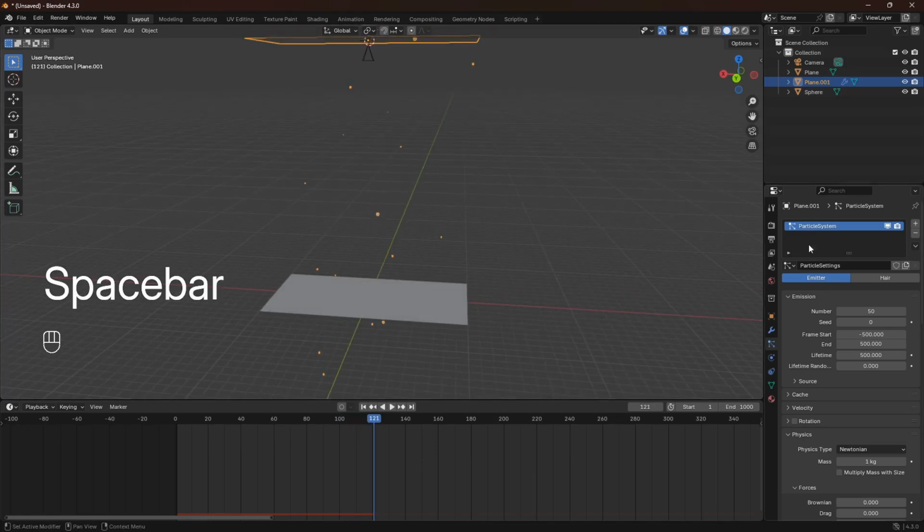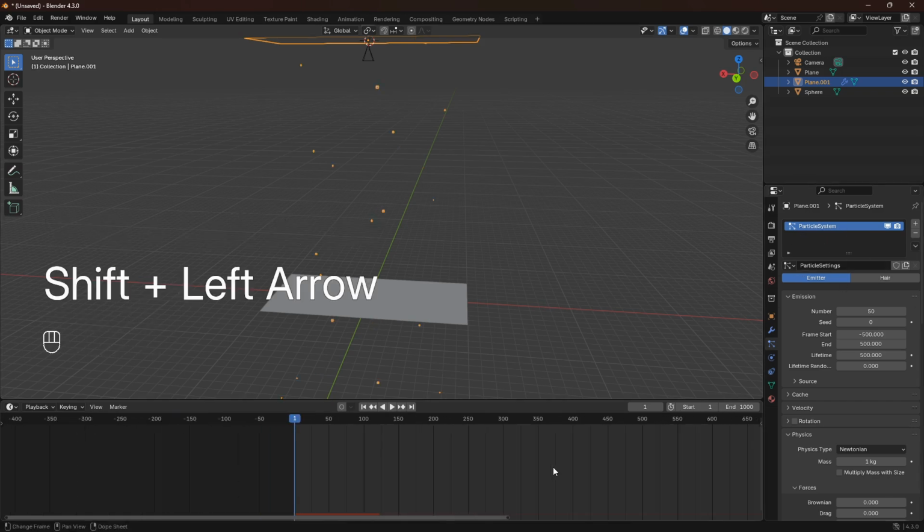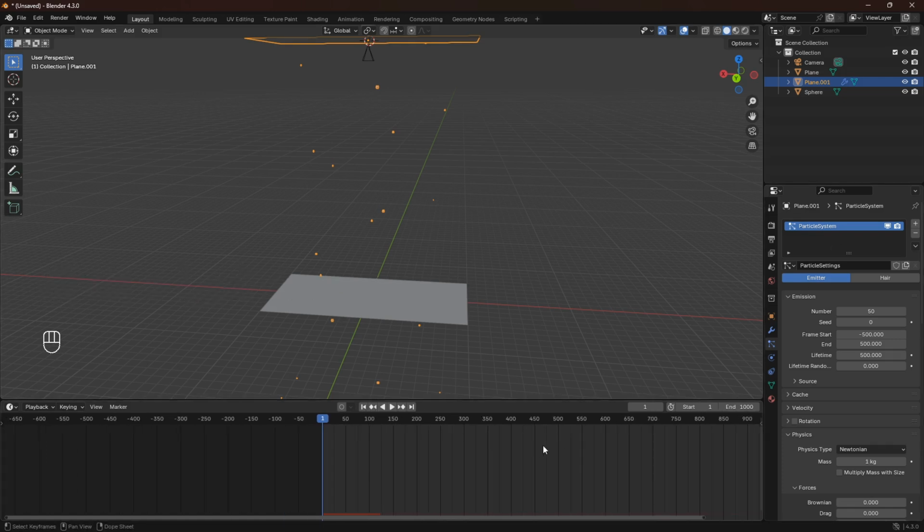let's just finish up this looping particle system here. So since we want to loop this particle system, we want to duplicate the particle system. So we want a second particle system overlapping with the first one. And to do that, we can just click onto this plus icon here. And we can go down to this little drop down window and then go to duplicate particle system and then select the second particle system. And also, really important, remember to click this little icon here for new particle settings.